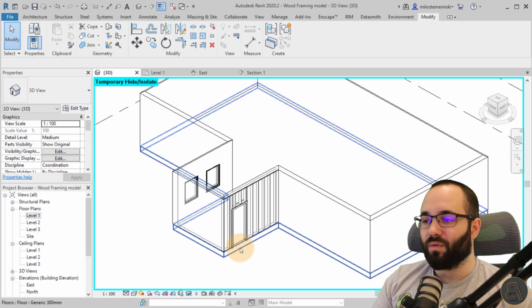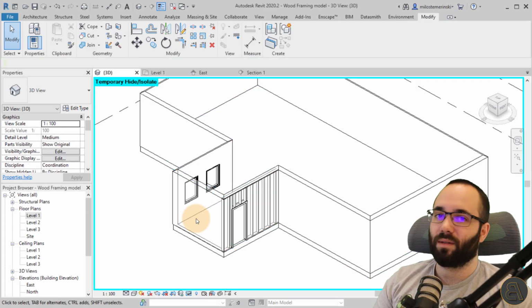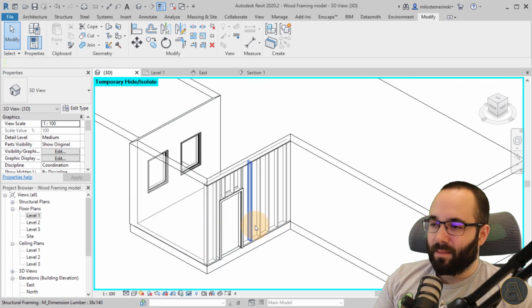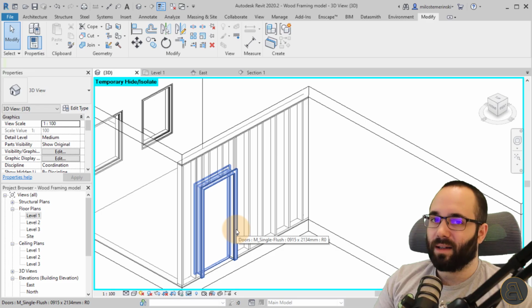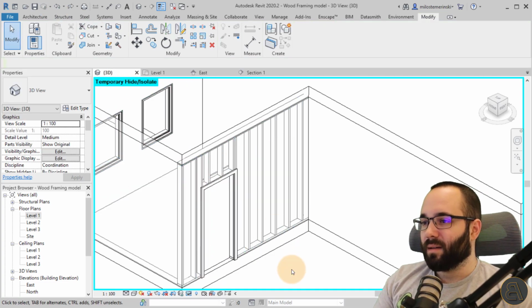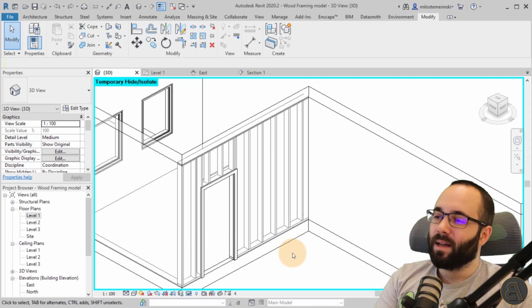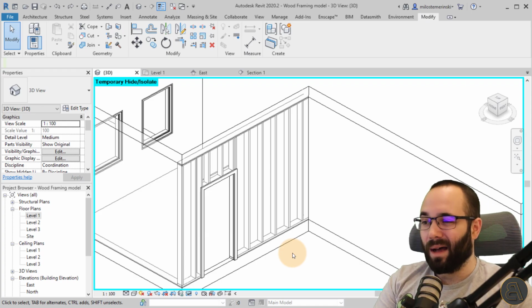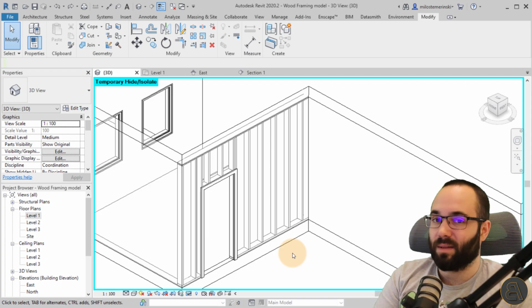You can use this approach for the floors, for walls, for roofs. It does take some time, and also if you don't lock everything in place, which is really a lot of work, when you move the door, it doesn't move with it. So it can be quite annoying. So what I would recommend is, once you finalize the design, that's when you start this framing process, because otherwise if you're changing the design while framing it, it is going to give you a lot of issues and a lot of trouble. So I would avoid doing that as long as it's possible, of course.